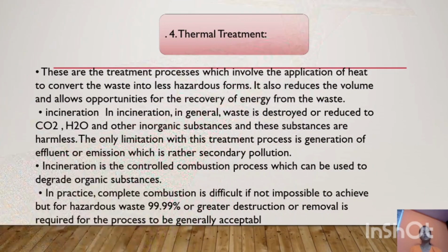So let's come to the thermal treatment. Incineration is a controlled combustion process which can be used to degrade organic substances. In practice, complete combustion is difficult. It is not impossible to achieve, but for hazardous waste, 99.99% destruction or removal is required for the process to be generally acceptable.